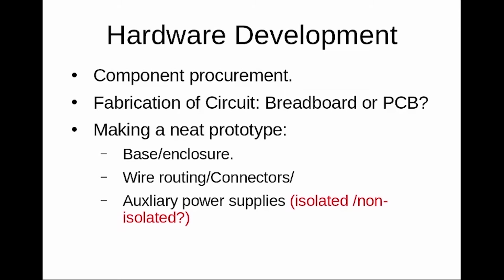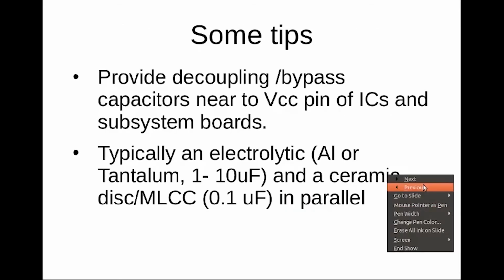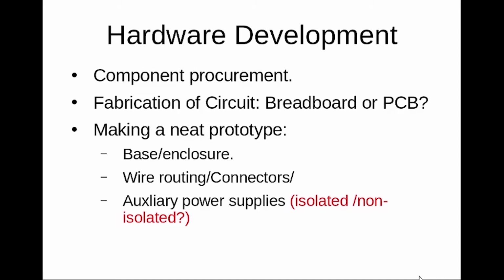When making a prototype, if the circuit is tested and bugs are corrected, you may think of presenting your prototype in a neat way. It could be either open or closed. You may adopt an open type prototype where the wiring, connectors, PCBs, contactors, and relays, etc. are mounted on a flat board, usually Hylam sheet or thin MDF board. Otherwise, you may also house your prototype inside an enclosure, plastic or sheet metal based, depending on your budget.